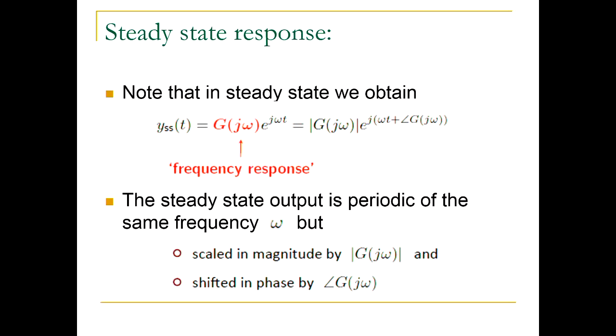So obviously the model of the system, the transfer function, in this case mass, determines the transfer function, and the transfer function determines what would be the output amplitude and the output phase. This is a property, I emphasize, of linear time invariant stable systems. If you have a nonlinear system, forget about frequency domain analysis. Generalizations to nonlinear systems are very limited. They are not general. So this is a very powerful method for linear systems. If you have some nonlinearity, forget about it.